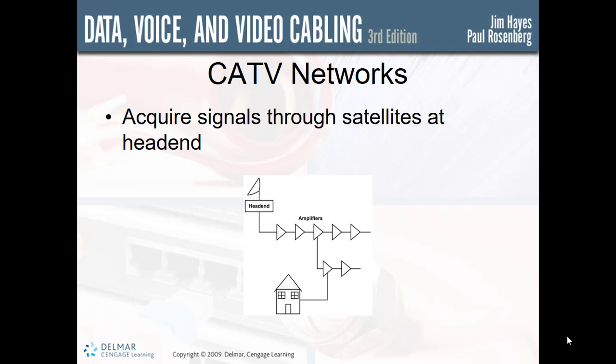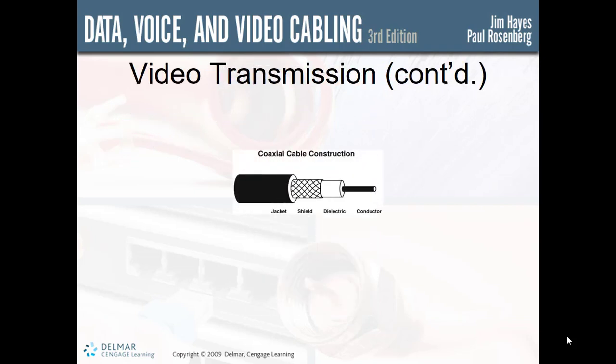So when the technology was first developed, the only cable capable of carrying these high-speed signals with adequately low loss was coax cable, also called coaxial cable. Now it uses a central conductor surrounded by an insulator. Then the outer conductor, or conductive webbing, called the shield, and then finally a plastic jacket. It's the design of the cable with the central conductor widely and evenly separated from the outer conductor that gives it the high bandwidth capability.